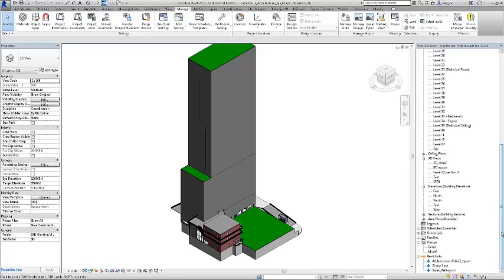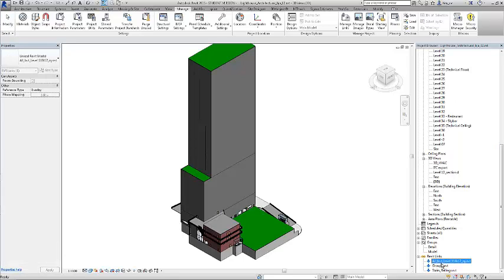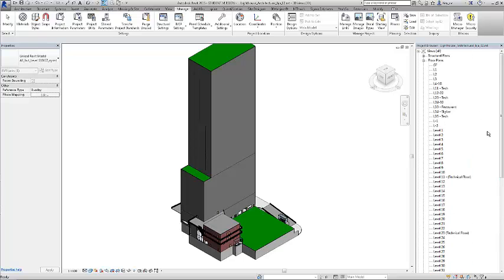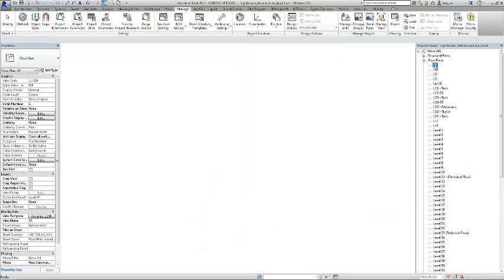And I have 3 links in the model. Stairs: I grouped all the stairs and railings, and then I created a stair and railing file. I grouped all the levels I do not have to use, and then saved it as a Revit file, and linked the model in. In this model I can see nearly all the things I could in the original.